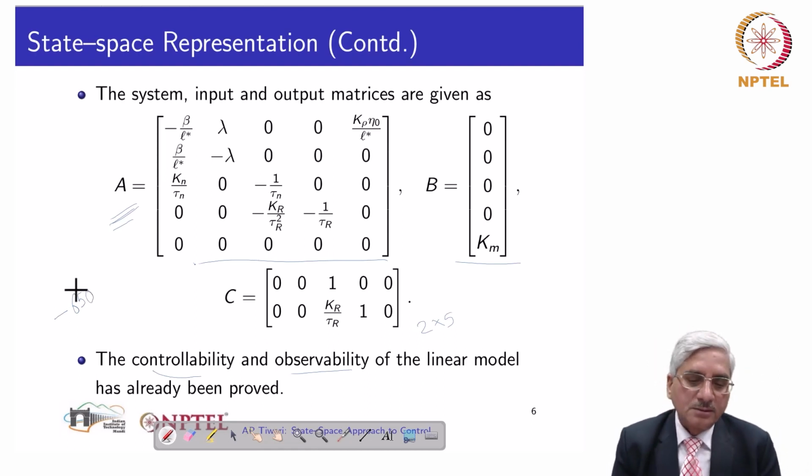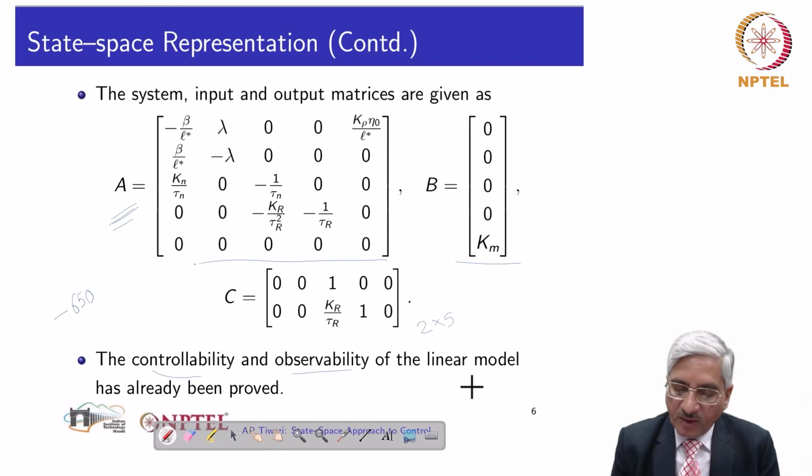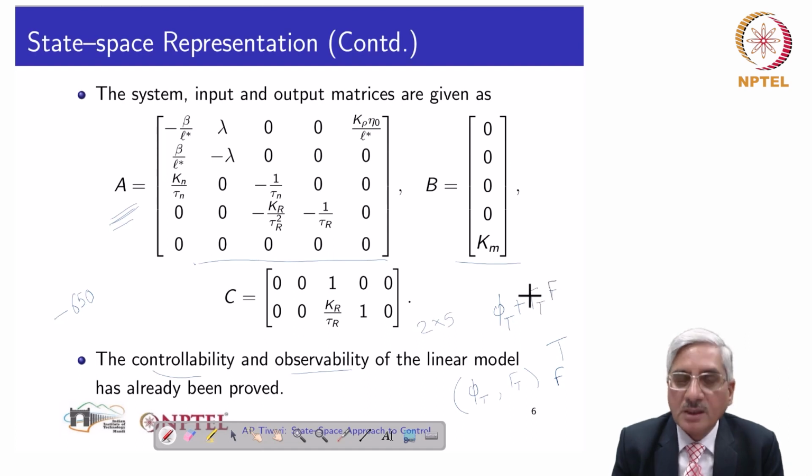Second thing is that an important consideration in the design of fast output sampling based controller is that we are required to design a state feedback for the system phi t gamma t, which is the discretized system for AB corresponding to the sampling time t. Now that with the state feedback f for the system, this closed loop system phi t plus gamma t f, this closed loop system matrix should be invertible.